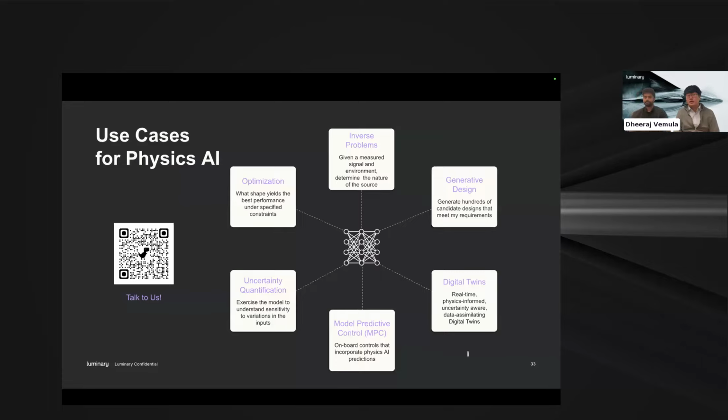There's two things that happen. One, you get a very rich amount of information. So, for example, my background is in hypersonics, so this is an analogy I will use. If you're doing any sort of TPS or thermal protection system sizing, it allows you to use that and then also do multi-objective optimization based on center of mass requirements for stability.